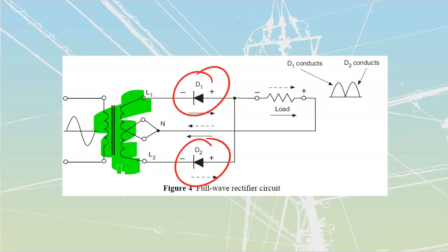Now, in a lot of cases, we are already having to step down from our line value voltage, 120 volts RMS coming in. We're usually going to be stepping that down to a lower value voltage to operate our DC, because a lot of our DC is going to operate off of what we refer to as TTL levels. TTL stands for transistor-transistor logic. That's going to be 0 and 5 volts generally. We do have some CMOS levels as well that will go up to about 12 volts, but most of our electronic components will be down inside of that 5 volts when we're looking at them as electronic actuations.